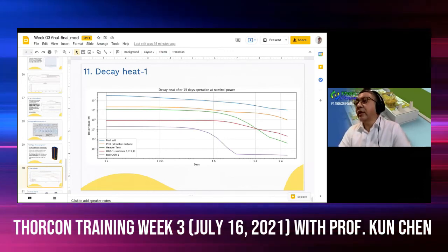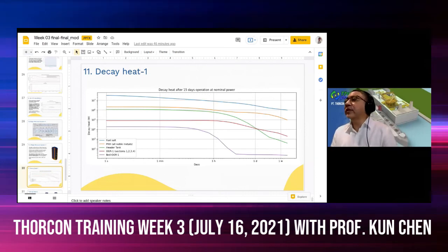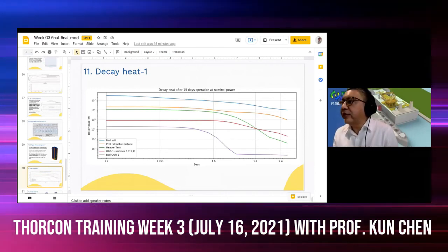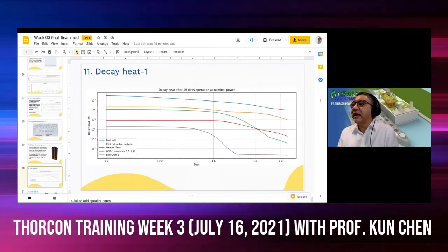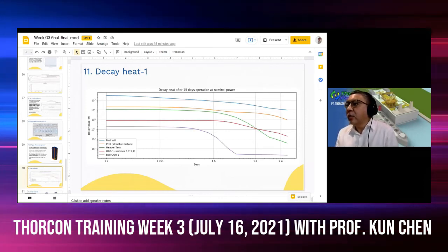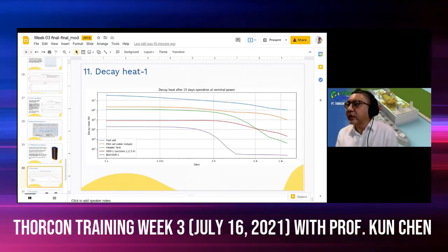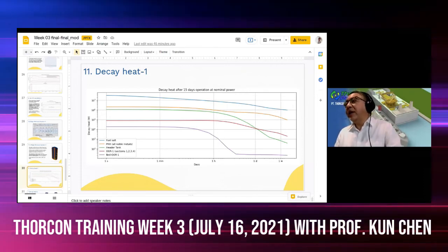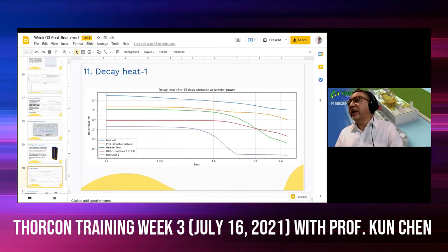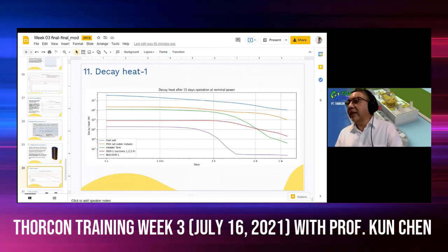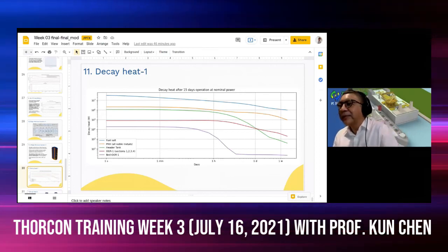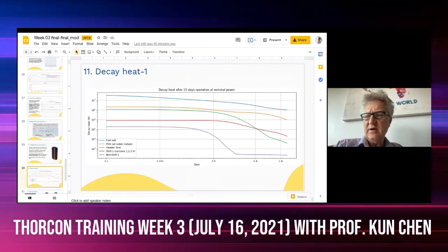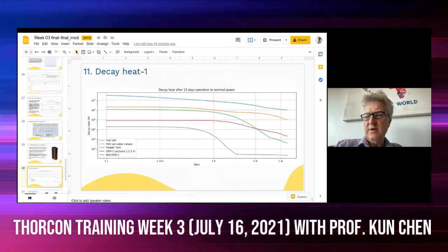All right, so I hope that answered Dr. Siddiq. So the next one, from Professor Juarez: the freeze valve design is exactly the same as has been used in Oak Ridge. What is the influence of the fuel salt type, since MSRE uses FLiBe and ThorCon uses NaBe? Yeah, so NaBe has a slightly higher melting point than FLiBe.